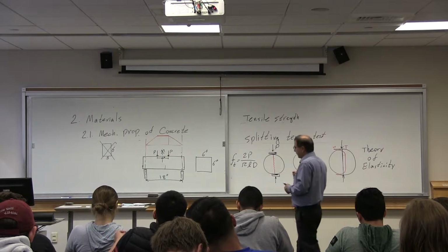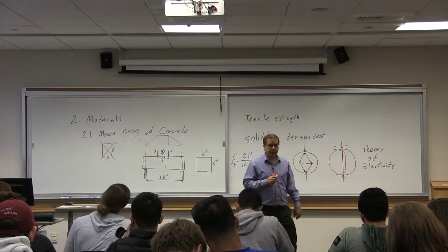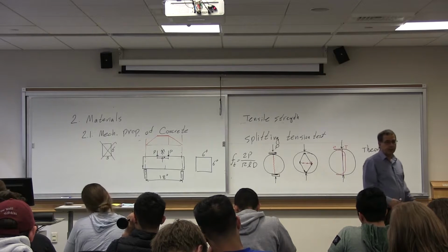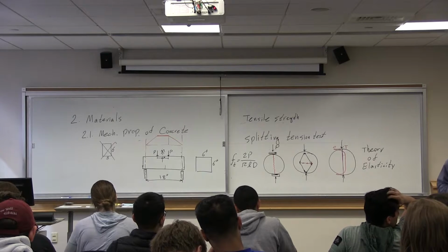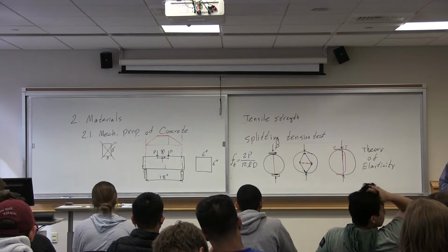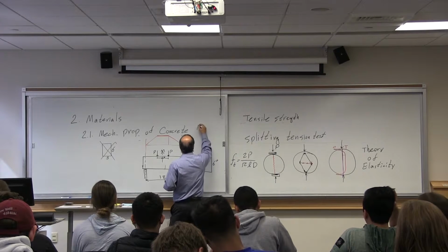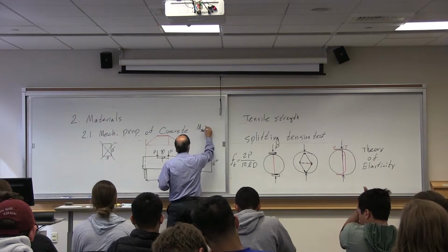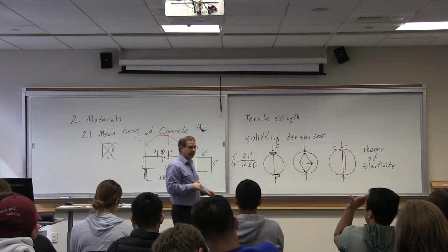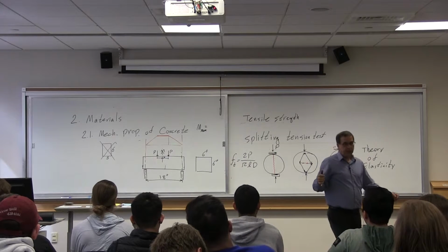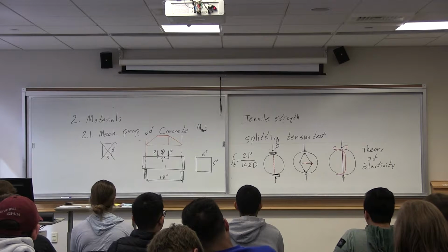So when you run this test, how can you get the concrete tensile strength from the test? Did you calculate it? How did you do that? It's a little longer. Once you get the maximum, you'd first need the maximum moment. What is the maximum moment? The actual test will show you where the maximum is. But let's say we want to do it here based on our knowledge of statics. If you have a beam with load applied at P with this geometry, what is the maximum moment?